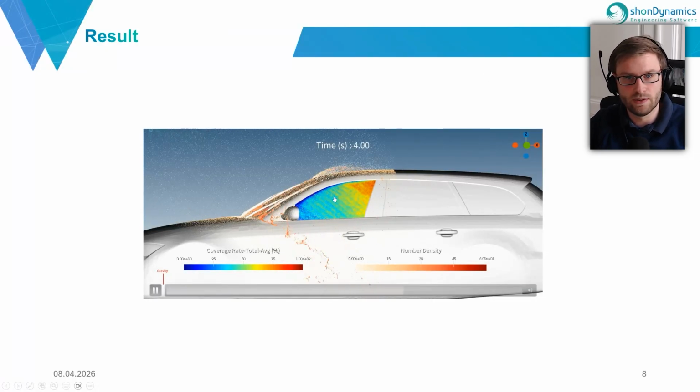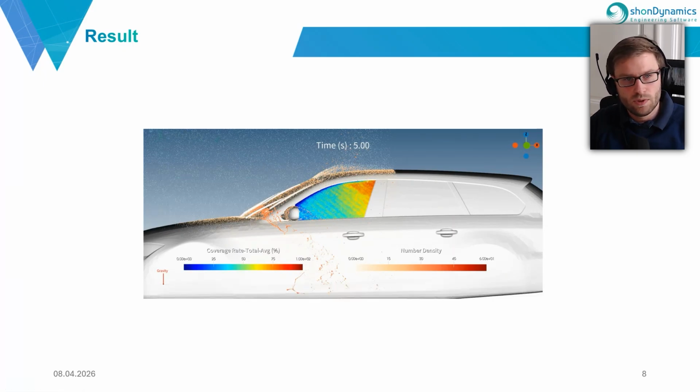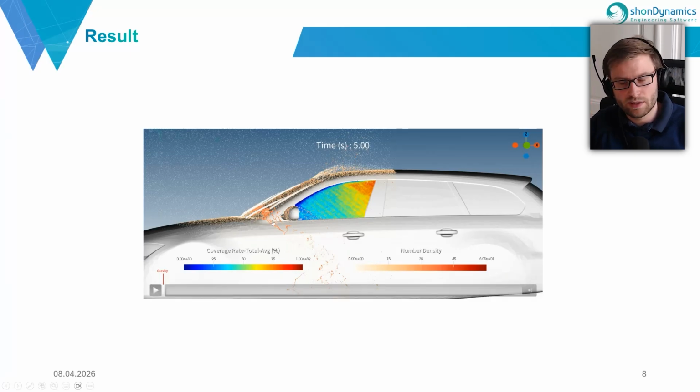So this is again our multi-body results, and this would be now our final simulation result with different kinds of post-processing options. For the water, I always used the number density as variable. This means the number density is a value for how many neighbors a particle has, and this means in the other direction, how many chunks of fluid are at one point.